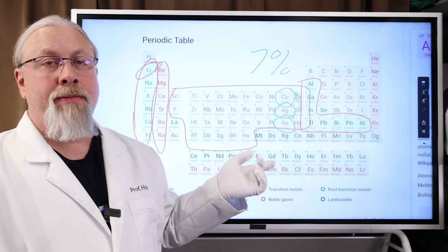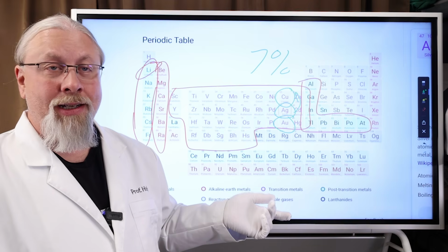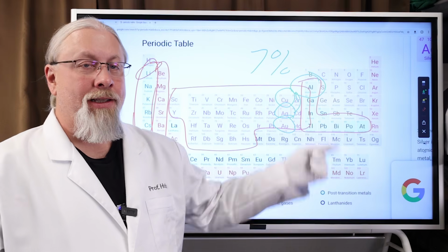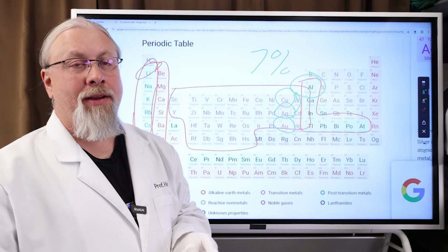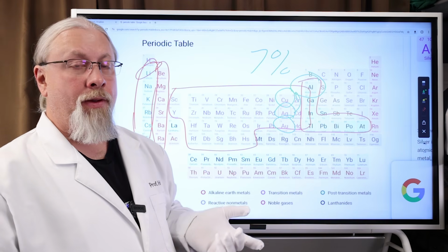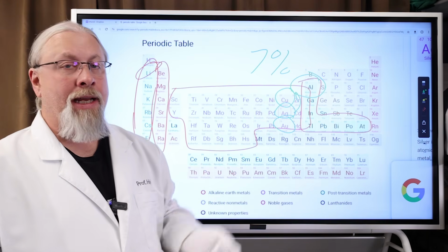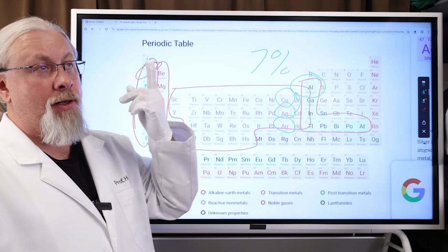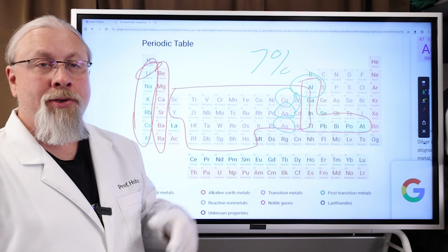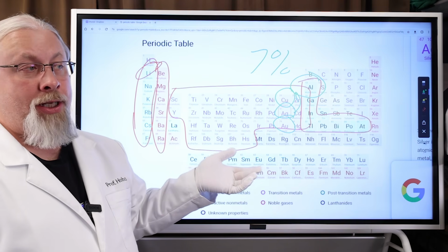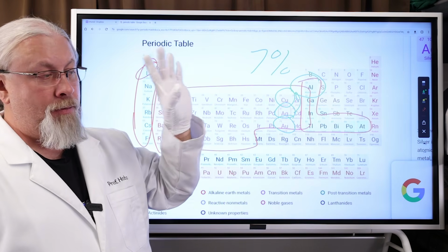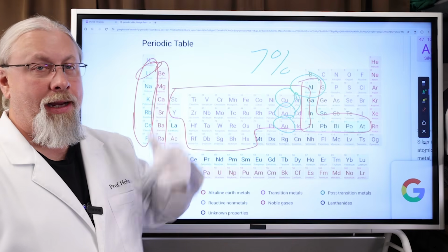Now, another metal that has started to make a comeback as an electrical conductor isn't really that great of a conductor compared to copper, and that is aluminum. Aluminum is only 61% of the conductivity of copper. However, at only 7 cents an ounce, or about a third of the cost of copper, aluminum is actually used in large power cables. So when you look up and see the cables running across the country on those big towers, those are made of aluminum because it's so much cheaper and it's only 30% of the weight of copper. So you have lightweight, much bigger, much cheaper cables running high tension lines.